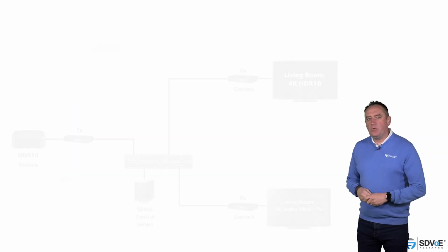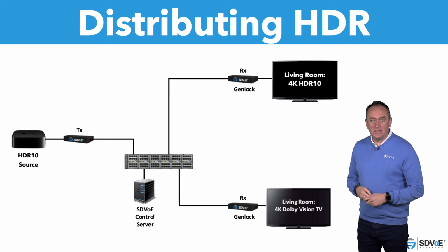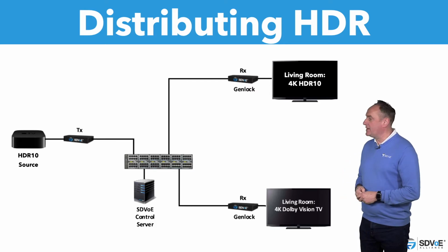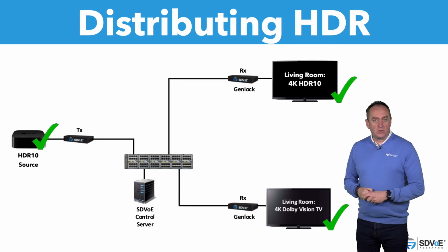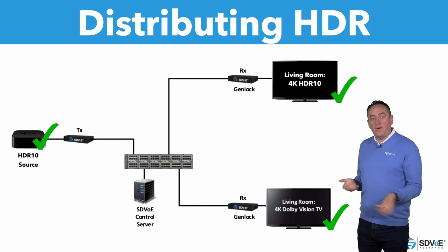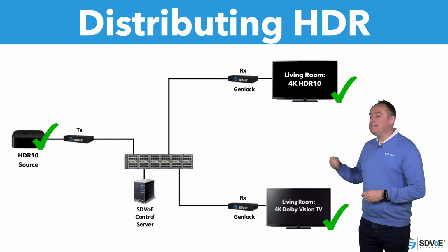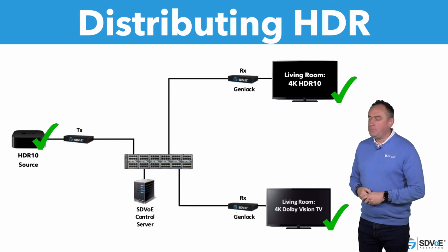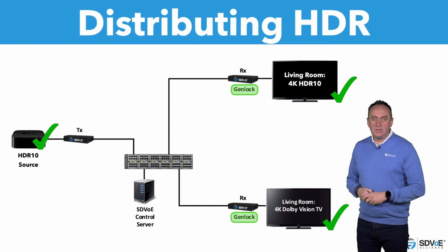Let's start by seeing what happens if an HDR10 or HDR10 Plus signal is distributed to multiple displays. If the displays are both compatible with the stream being sent, then both displays will work fine, providing that the transport system maintains the metadata and delivers it to the displays. SDVoE does exactly this in Genlock mode.